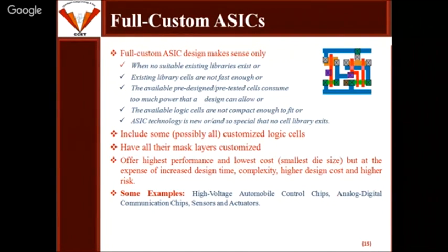It offers highest performance, lowest cost. We are basically comparing it with the semi-custom design. This is going to offer the highest performance and lower cost, but at the expense of increased design time and higher design cost, because we are putting in each and every effort. So time will be more as well as cost will be higher. Some examples are high voltage automobile control chips, analog to digital communication chips, sensors and actuators. Those we have to design in a full custom hierarchy.